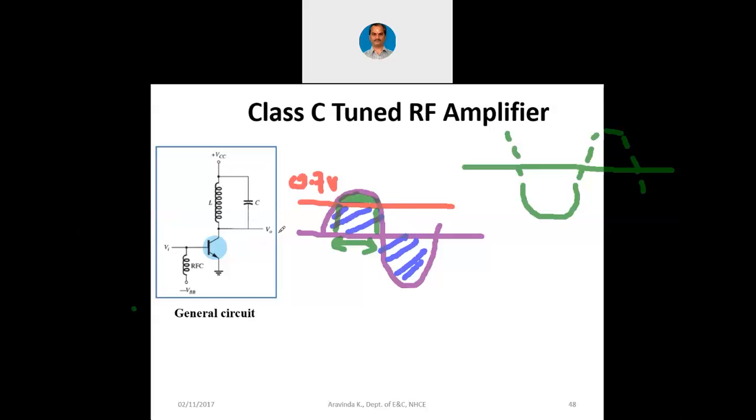In the same way, here when we use the radio frequency wave as a carrier wave for carrying the information signal, the carrier wave shape is not going to be important because anyhow it is going to be modulated either by means of amplitude modulation or frequency modulation or phase modulation. In that way, the information signal's shape is important, the carrier signal's shape is not important. There we make a compromise.